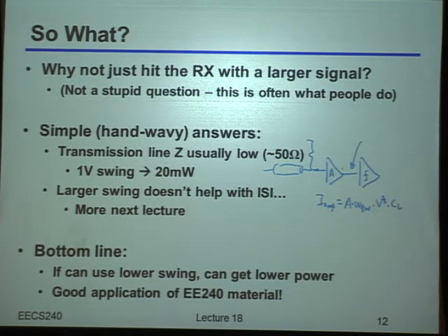Okay. So that load capacitance, of course, is just coming from the comparator. Just as an example, in the project, what did I tell you the capacitance was for that comparator? 50 femto. Okay? Turns out that's even probably higher than it really needs to be. Now, again, why is it that I claim that this number is probably a lot smaller than what it would take me to just increase my swing on the transmitter? What does that have to compare against what?